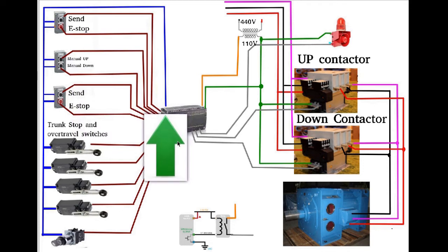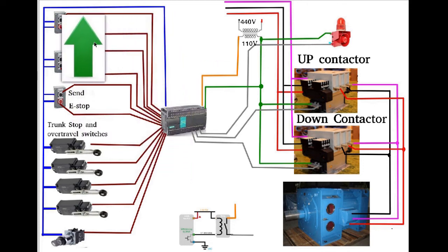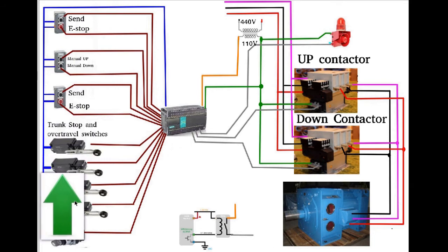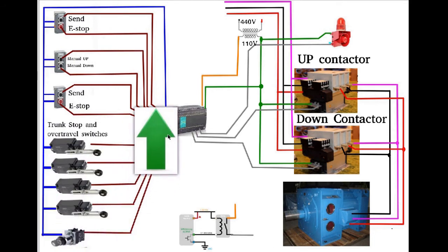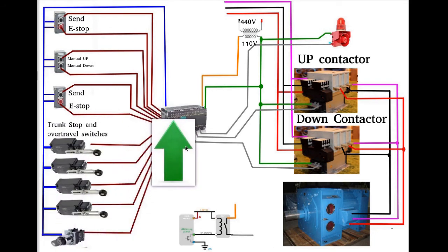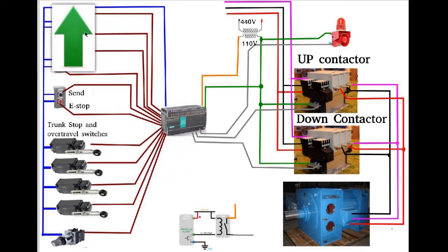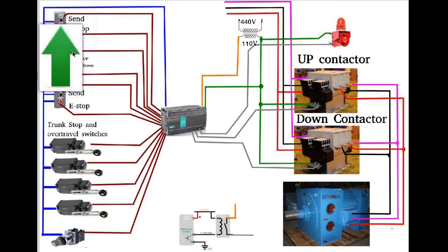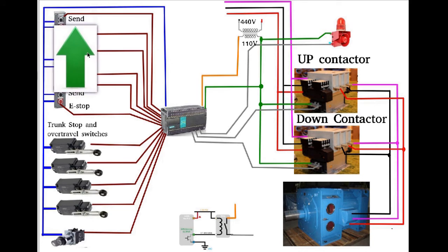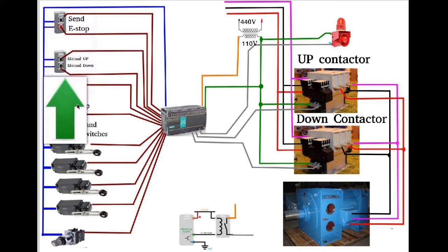The inputs over here, I put a blue line indicating that it's 24 volts that the PLC is providing. This is not the only allowable solution, especially if the PLC has what is called optocouplers. But anyway, the assumption, or the disclaimer, is that all of these push buttons and all of these switches are normally open, to include the key switch.